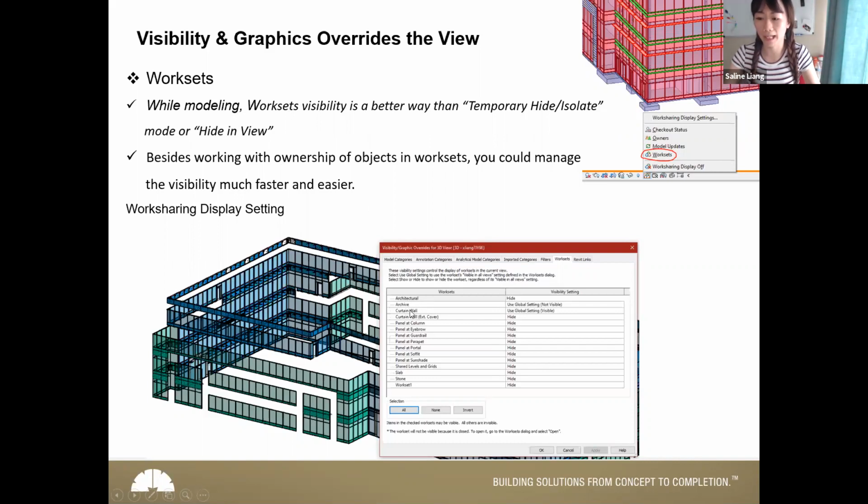If you set it up nicely, you have different worksets. You can make whatever more categories. It doesn't need to be like this, but this is my first project that has so many worksets compared to past projects. So in the beginning, you just set it up with a blank workset after you collaborate your model, and then you can assign the model into the workset under the properties. I can show that a little bit later.